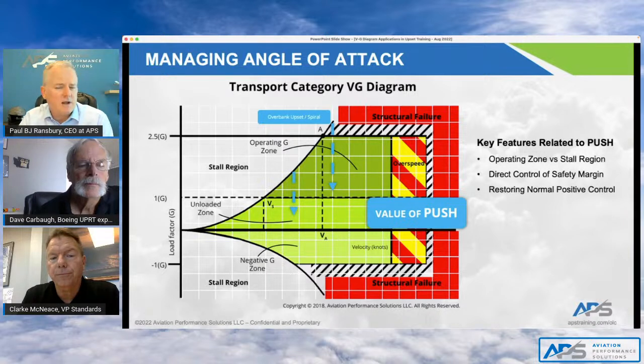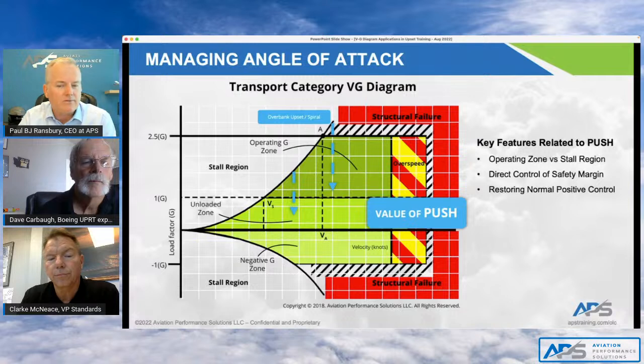Awesome. And then, of course, I want to bring up the slower speed one for the same situation. The point of this is, in fact, we have an animation coming up where the pilot is very much closer to that new blue arrow, that second blue arrow. And in this particular scenario, yes, instead of the load limit being the threat, the stall could be the threat in an overbank if you're at lower airspeed, like a wake turbulence encounter. But fundamentally, the principle of recovery is transferable and largely the same. And it's important to understand those 6 factors that we listed earlier, to be addressed typically in a standardized order to help mitigate a wide diversity of situations.